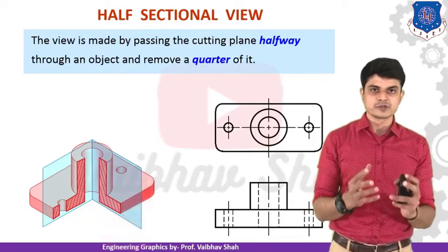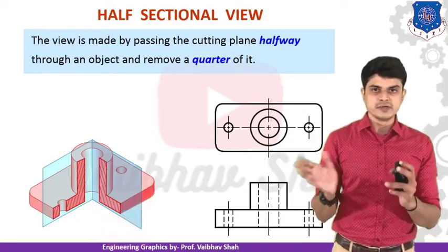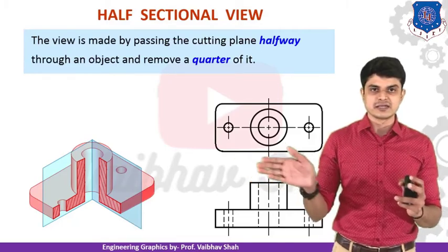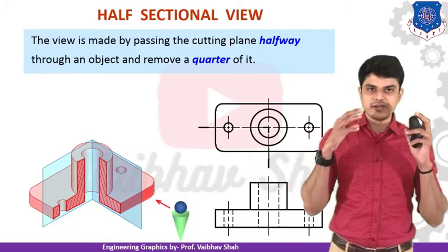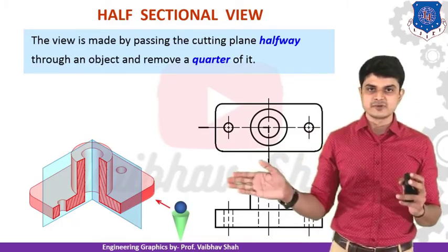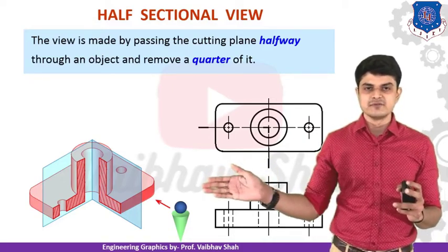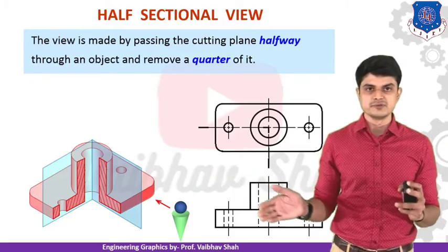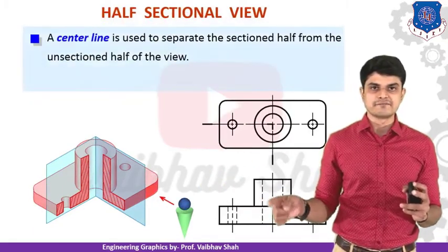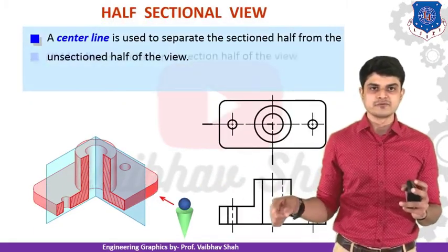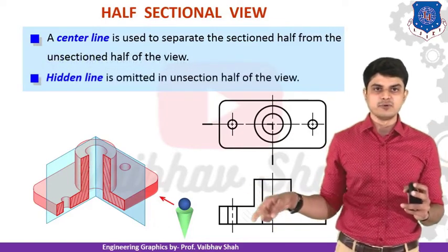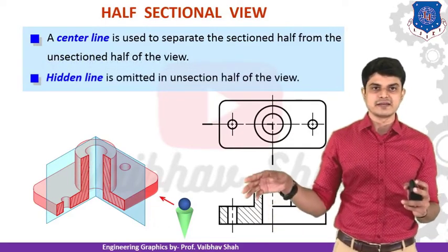So it is a quarter portion, or one-fourth portion, that is now removed. So in the front view you can see the section now. When you observe this image from this side, the left hand side portion would be removed, so you can see the section view on the left hand side of your observer. You will have this portion on the left hand side, made by removing the dotted line, and you should give the hatching line to that.